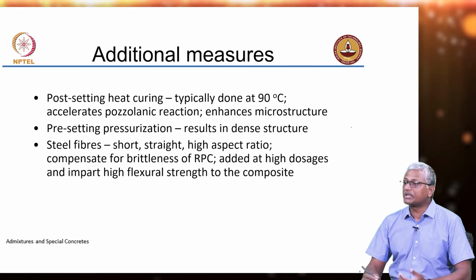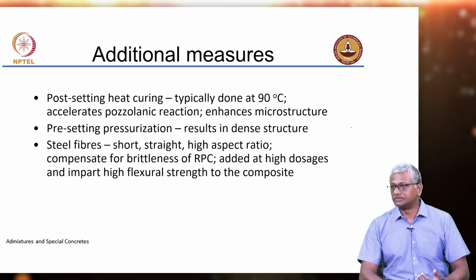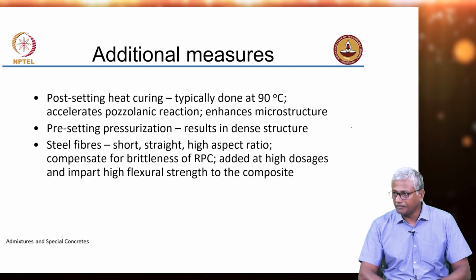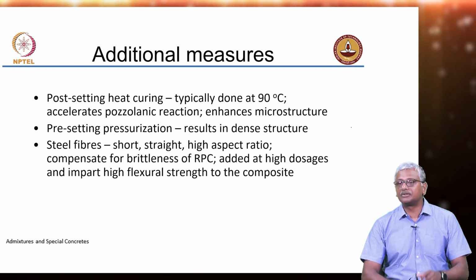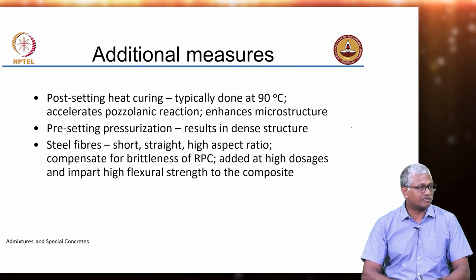Post-setting heat curing, typically done at 90 degrees Celsius. It is a very high temperature, 90 degrees is a very high temperature. It cannot be sustained for a long period of time. You can sustain it during the initial steam curing period, like in most precast factories.